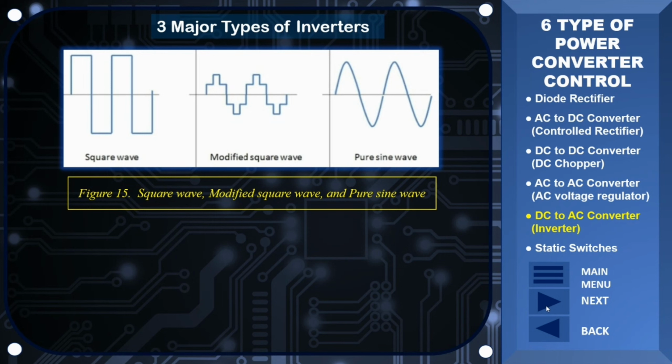Second, modified sine wave. Actually, a modified sine wave inverter has a waveform more like a square wave but with an extra step or so. A lot of equipment will work well on modified sine wave inverters, including motors, household appliances, and other items. Some types of load can be problematic and do require a pure sine wave converter.